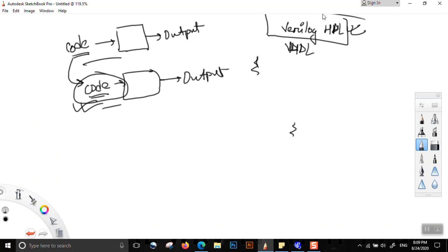The advantage that hardware description language possesses, especially in case of VLSI, is that if you have Cadence, which is a software for layout design or chip IC design, we can just write a code in Verilog HDL, and it automatically will create the circuit for us. So the digital design entirely depends on our hardware description language.